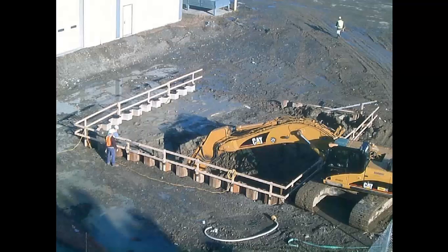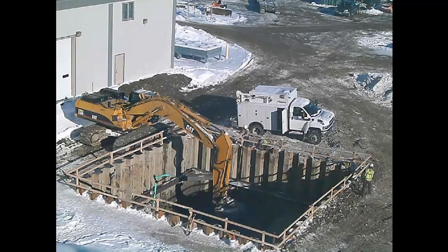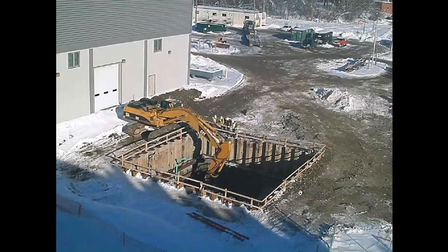We're going to start excavating out of this site. So they start excavating. They still had some sheet piles to put in here because they left that open so that the drillers could get in. Continue excavating. They're excavating right to the sheet piles. So we're creating this basically wall around the outside. They've got some welded steel reinforcing along the perimeter, and they're just digging down as far as they can. It gets down to the point where they're pretty much stretching it.